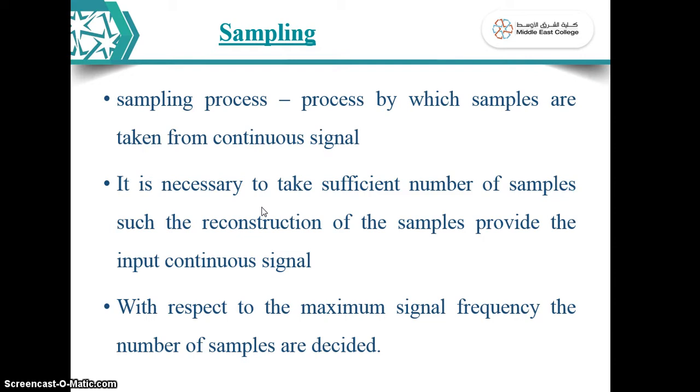samples. So normally, how many samples should be taken when we convert an analog signal to a digital signal, or a continuous time message signal? When we are discretizing it, how many samples do we need to take? It depends on the maximum frequency of your analog message signal. So how many samples should be taken for discretizing depends on the maximum frequency present in the message signal. According to that, if we have taken the samples, only then will we be able to reconstruct it. So we will see in detail how it is.